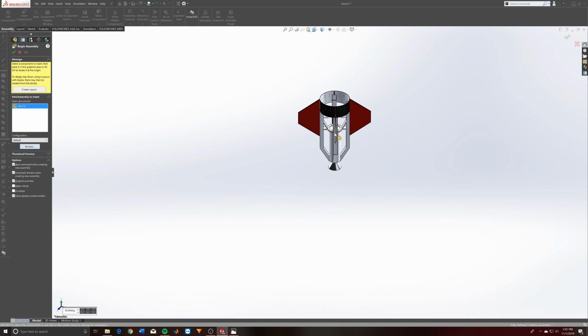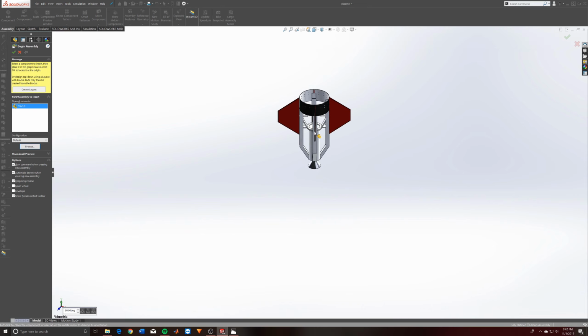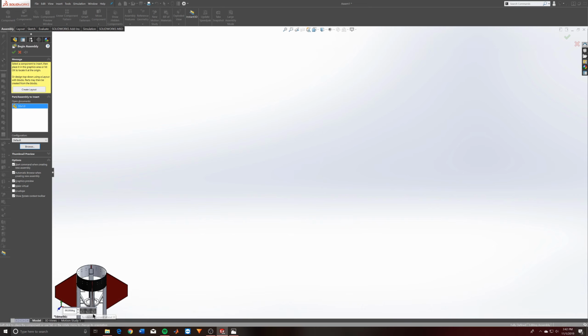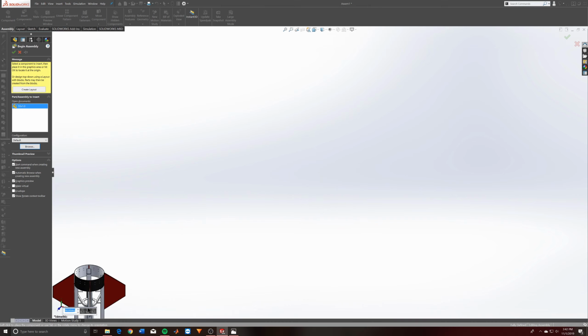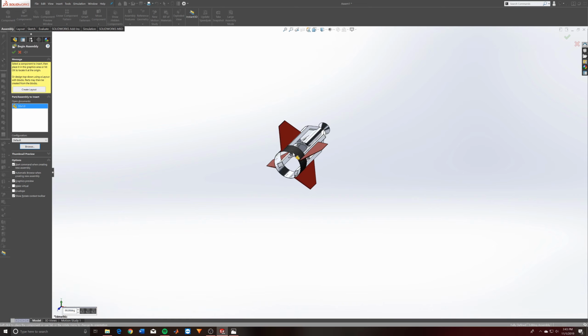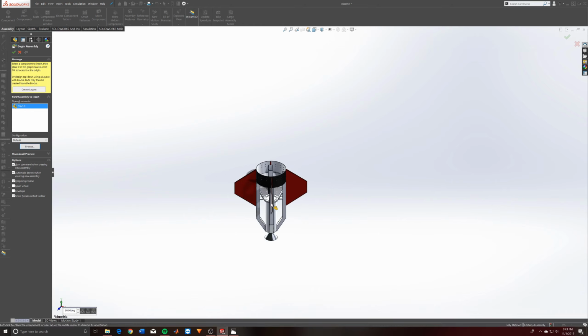And something really cool that is really helpful after a while, if you have a bunch of parts and you need to orient a part a certain way and it doesn't come out the right way here, what you can actually do is in the lower left hand corner you see an XYZ rotation component. You can rotate by 90 degrees just by pressing these buttons, and you can edit the amount that it changes by on each click. So if you need this part to be flipped 90 degrees to the right or to the left, you can just do it like that and then place it in, and you'll be all set. So that's a cool little helpful way to get parts in the orientation that you want.